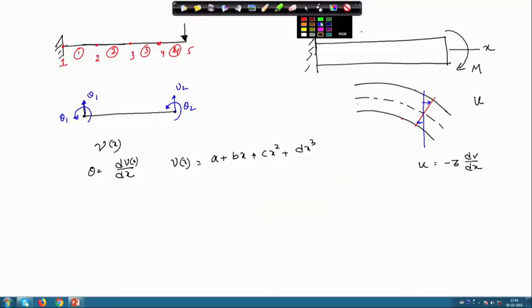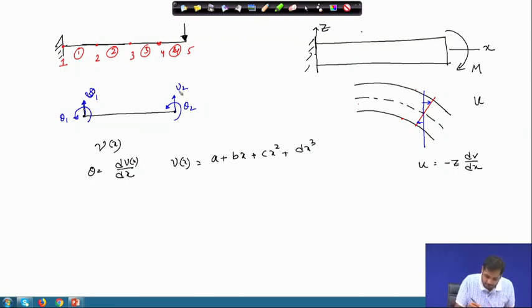In order to find those constants, we need a sufficient number of equations. In the case of truss, we had just two equations, and the premise of those equations was information about the nodal displacement. At every node we had just one displacement, so two nodes gave two pieces of information. With that information we could only calculate two constants. That is why our approximation was linear. But in this case we have four pieces of information. We know the transverse displacement v and rotation at node 1, and the transverse displacement and rotation at node 2. So, 4 unknowns; that is the reason we considered 4 constants here.